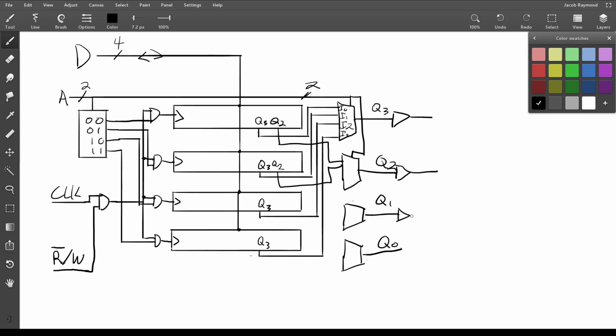And so we draw just a triangle, and then we'll have a secondary input coming into the side. We'll have it coming at the bottom here. And this input here, basically, if it's a 0, nothing's going to go through. It's just going to almost completely cut these wires off. But if the input is a 1, then it'll connect that wire, and the output of these Q3s would be able to pass through.